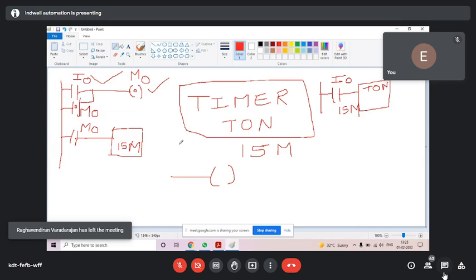But between the contact and coil, a timer is not allowed to apply in that one ladder. It is a single error. Simply understand that we cannot latch a timer. After timer, I shall explain timer. We'll learn that. But here, what did we learn? That a flag is required. Without a flag, it is not possible to run an on delay timer. That we understood by this example.